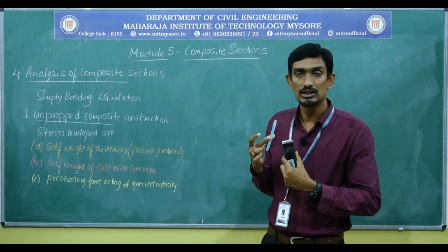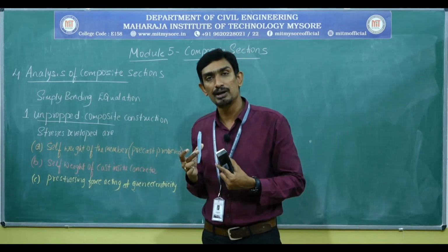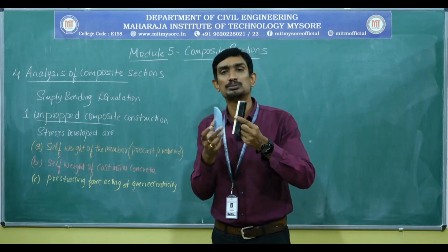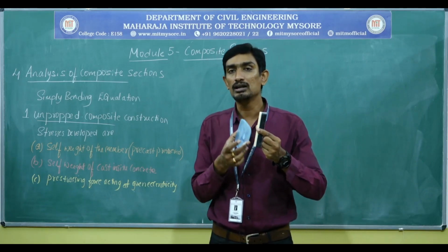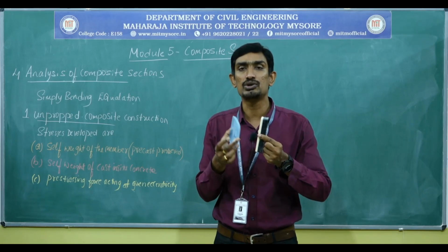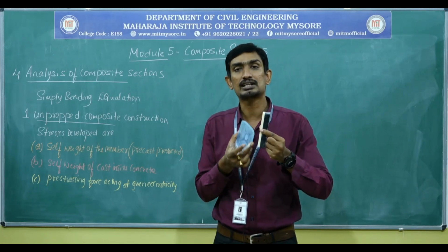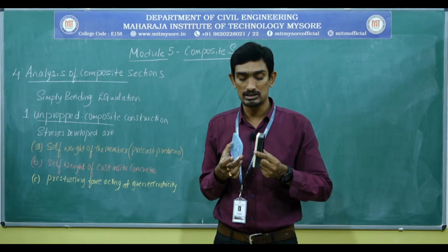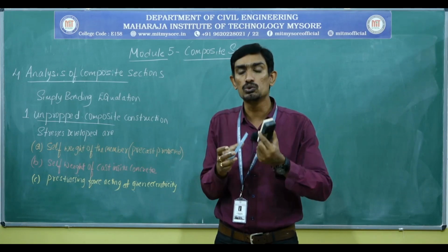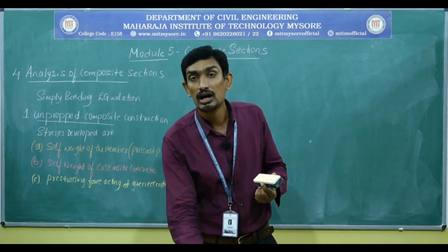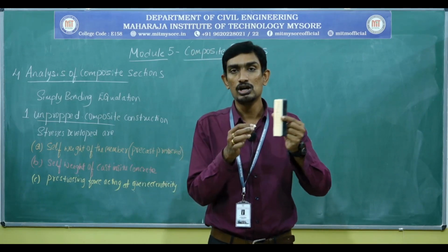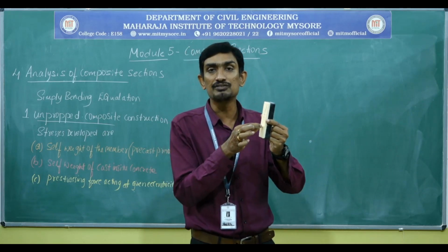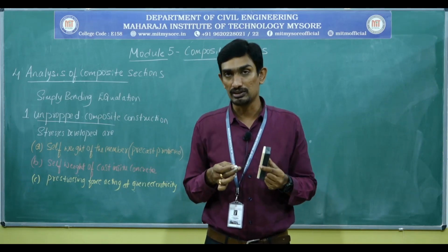Apart from these two, we already know from the basic principles of pre-stressing in module number 1 that while manufacturing the precast pre-stressed unit in the factory, I induce a pre-stressing force at a particular distance, that is, at an eccentricity.